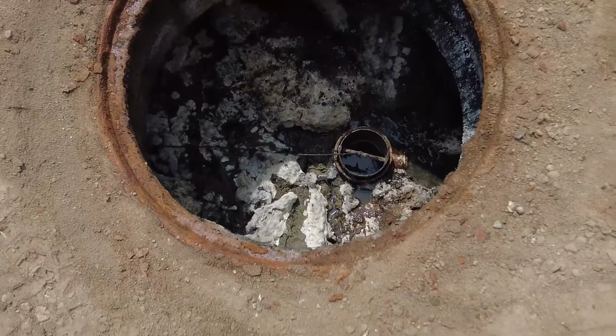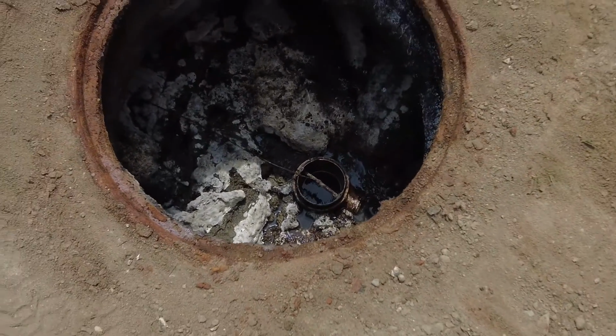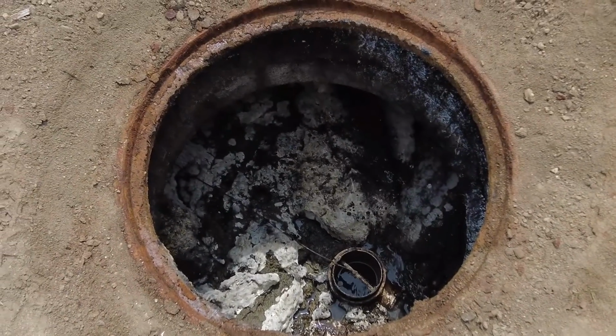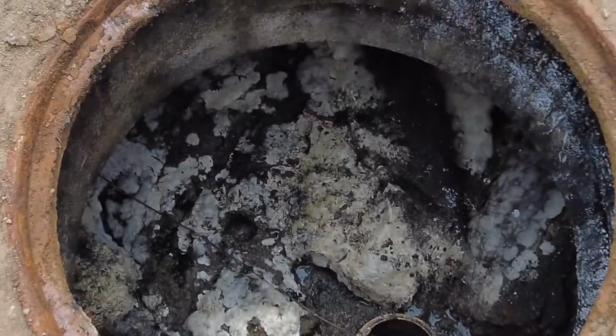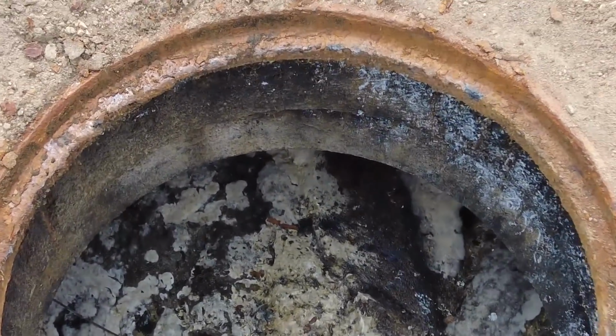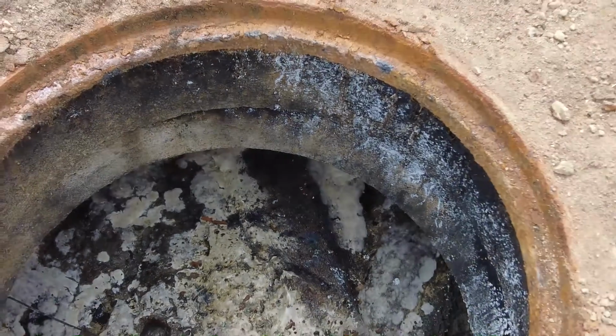Look at that influent. Try to get a good influent number. Even if you can't get a good influent number, if you go to the influent side of that system and you measure the total nitrogen and it's up over 100, even if it's remixed, you know that there's more than the typical coming into it. So that gets a little bit into those extreme circumstances.